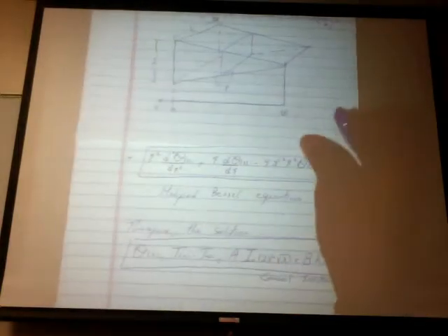So if you have a triangular fin, the temperature distribution and hence the amount of heat that you can remove, because the amount of heat that you remove because of the fin is proportional to dT/dx, right? Heat conduction, k dT/dx. So if you have a triangular fin, the solution is in terms of Bessel functions, modified Bessel functions of square root of x. And this gamma contains convection and conduction and size and so on, all that information.